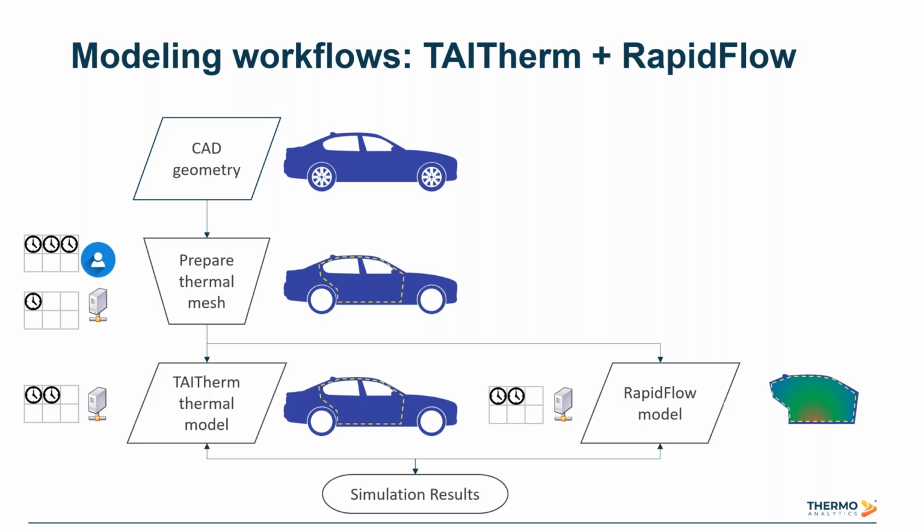So that'll give us the same sort of 3D flow and temperature discretization inside the cabin. And in this case, the coupling between thermal and fluid is automated, so kind of reducing some user burden there as well. So hopefully with a more modest computational cost and reduced user pre-processing time, we can achieve the same or similar level of fidelities to the CFD coupled approach.